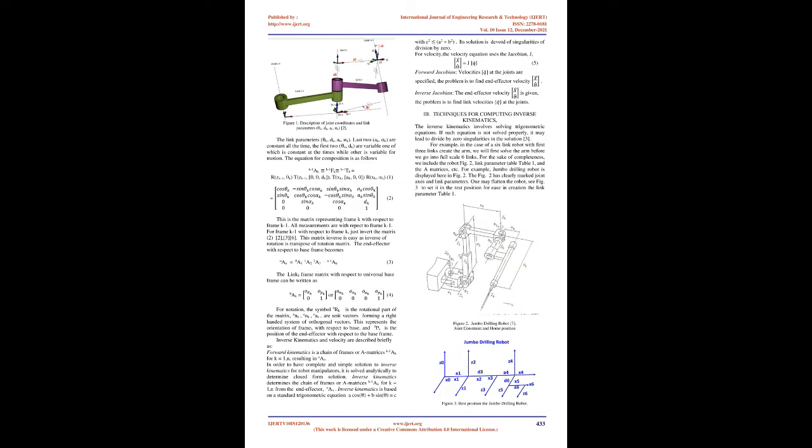As in forward kinematics, application of forward velocity is also straightforward. In fact, this becomes an issue only when the Jacobian is not a square matrix. It happens when the system of equations is underdetermined or overdetermined. For this inverse Jacobian problem, there are algebraic approaches to resolve this. We provide more efficient ways to grasp the concepts of inverse kinematics and inverse Jacobian.